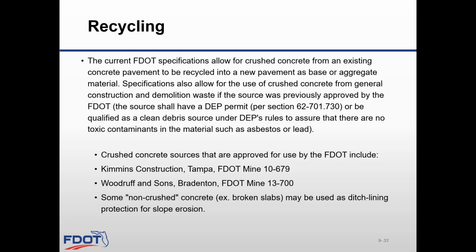In addition to the mentioned specifications, for FDOT, the source shall have a DEP permit per section 62-701.730, or be qualified as a clean debris source under DEP's rules to assure that there are no toxic contaminants in the materials such as asbestos or lead.